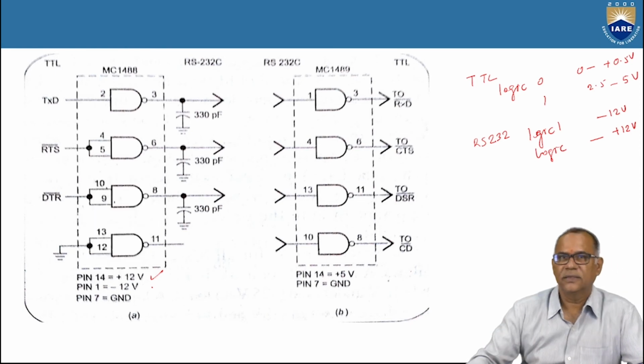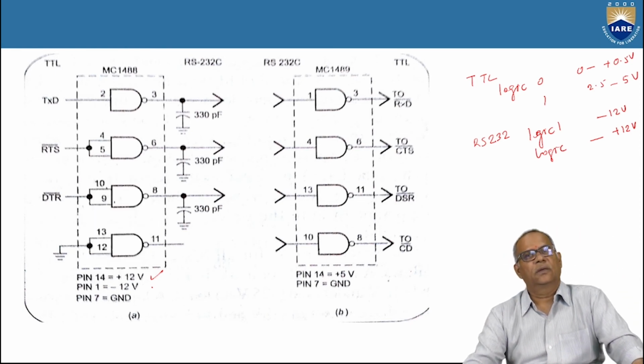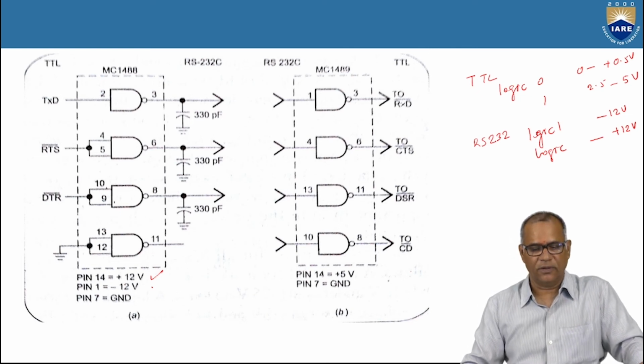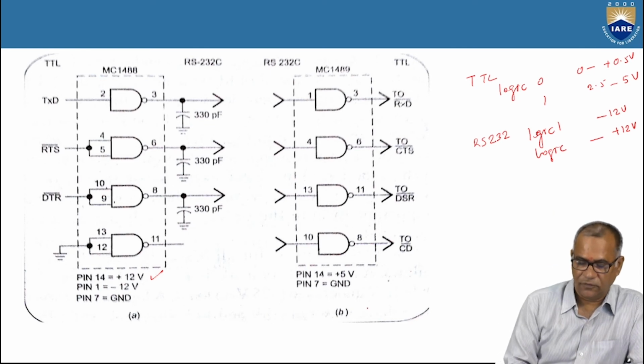And when data is received from the medium, it is in RS-232 form, and that is converted into TTL form using this MC1489 IC.